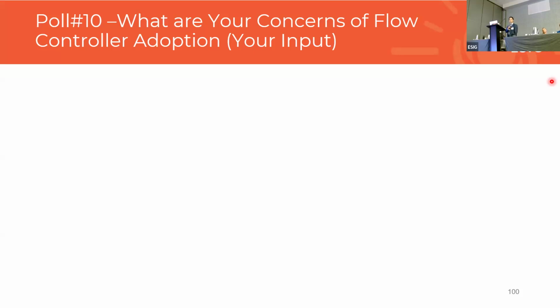Okay. So you estimated about $50,000 to install it. I assume it doesn't require breakers or MOVs. You just connect it in with a jumper. It's done. Essentially, yeah. You drop it on site, you have a riser going up the pole, and depending upon the control mode, I think right now all installations include two CTs, upstream and downstream, so you know what the neutral current is. Then it just pulls power down on all the phases and terminates in the device.